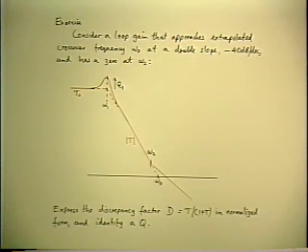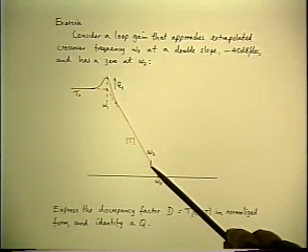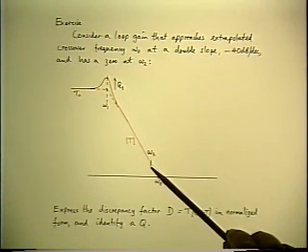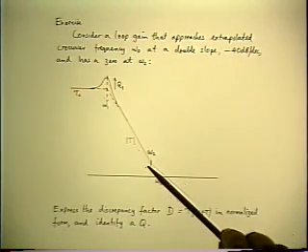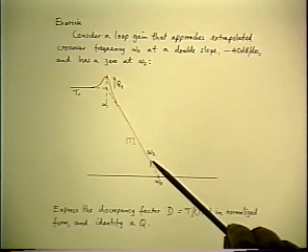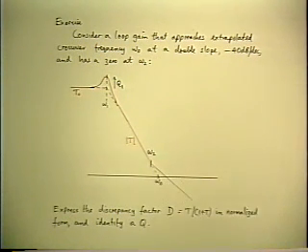But what had happened when they started using a different capacitor was that the reason they didn't oscillate in the first place was because the capacitor they were using puts a zero in this response. We did that already. That was one of the extensions of the original RLC filter. The last thing we put in was the capacitor ESR, and we found out it produces an additional zero. And that's what was stabilizing the loop, because it put this zero in at a nice low frequency, and so they built a good phase margin.